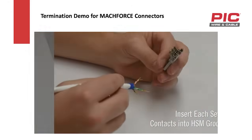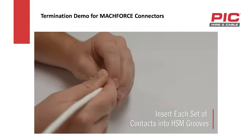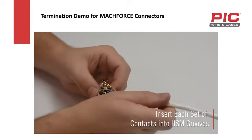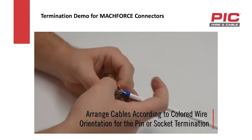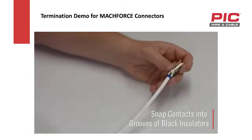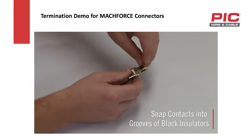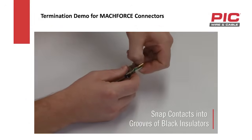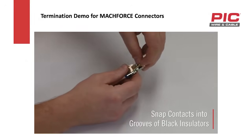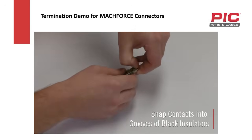Now we are going to install each set of twisted pairs into the HSM by opening the door on the HSM and inserting each set of contacts into the HSM grooves. When doing this, it is imperative to ensure that the cables are properly arranged for the correct pin or socket termination. The next step is to pull the contacts up to the insulators and snap them into the insulators.